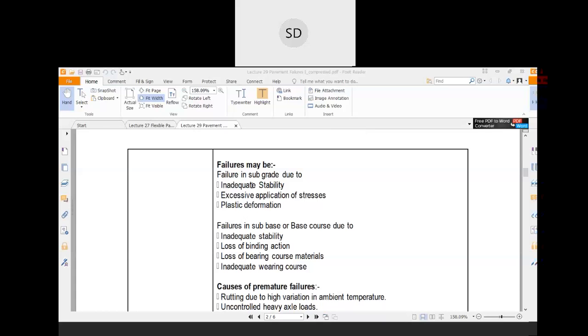And whenever there is some waterlogged area, in that case you can build a culvert or other type of structure so that water cannot penetrate through the pavement layers. Otherwise, your subgrade will fail and that will cause some permanent deformation.